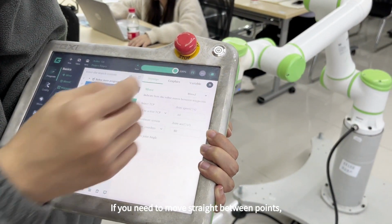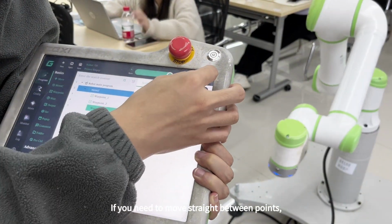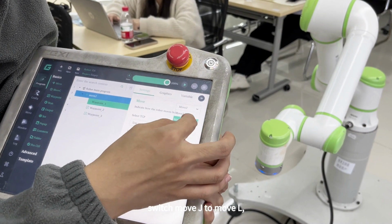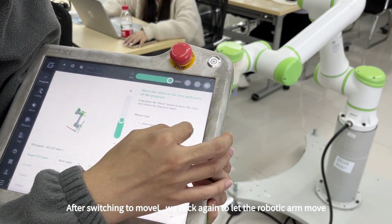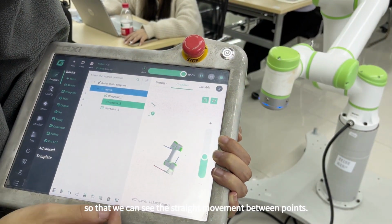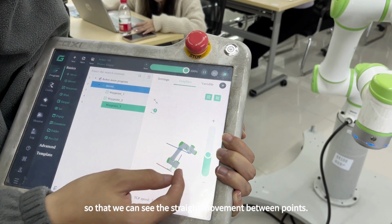If you need to move straight between points, switch Move J to Move L. After switching to Move L, we click again to let the robotic arm move, so that we can see the straight movement between points.